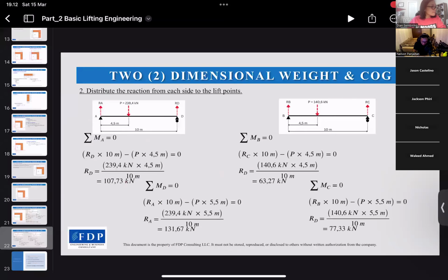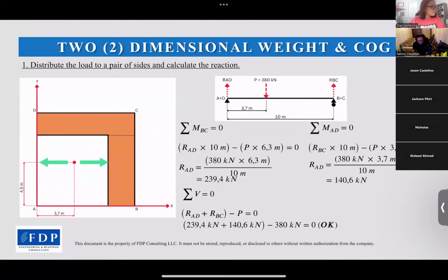So this calculation will be helpful to find the outrigger forces for the mobile crane. So we assume the cranes are a rigid structure, so there is no deflection introduced to get the lifting to the outrigger forces.